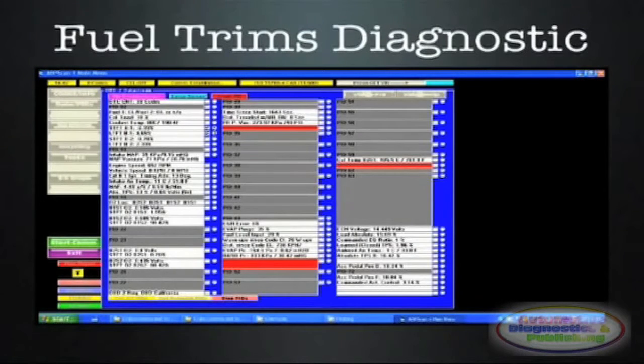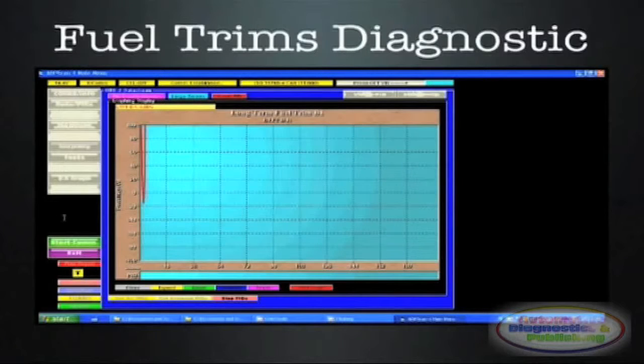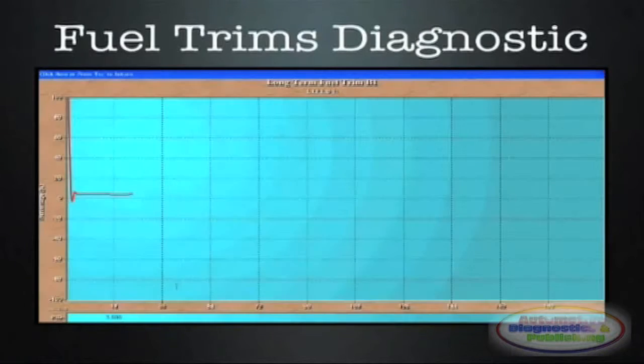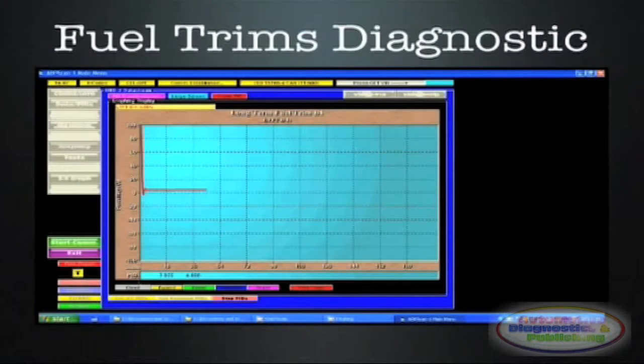The short-term fuel trim will always try to stay at 0. If it goes plus or minus, it will affect the long-term, and then go back to 0. Again, you need as much screen detail as possible. The speed of the scan tool is also important. The long term is very slow, meaning that this PID reacts to the more persistent air-fuel imbalance.